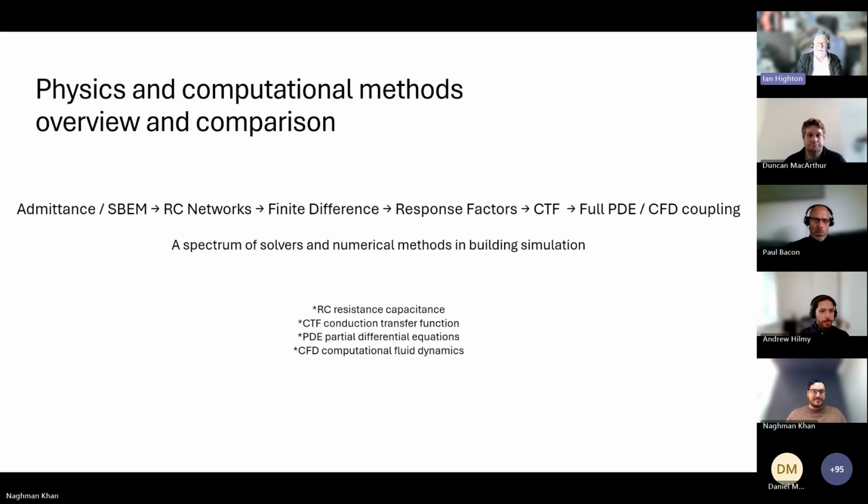Okay, admittance. I'm not an expert on this, and I'm not entirely sure how SBEM does it, but it basically does an energy balance per month. So that's 12 calculations compared to 8,760 for a DSM. Admittance was an interesting thing that CIBSE came up with, which was primarily created as a hand calculation, and this basically assumes that you've got sinusoidally varying weather or flat weather. So in the summer they'd have a sinusoidally varying infinite amount of time, but it allows you to come up with a sort of result, not a steady state result, because obviously it's got the sinusoidally varying summer temperatures. In the winter they generally just stick in -4, -6.